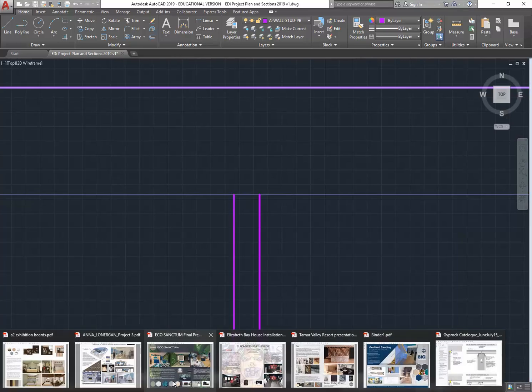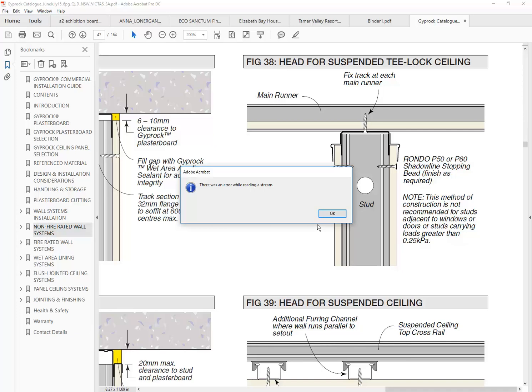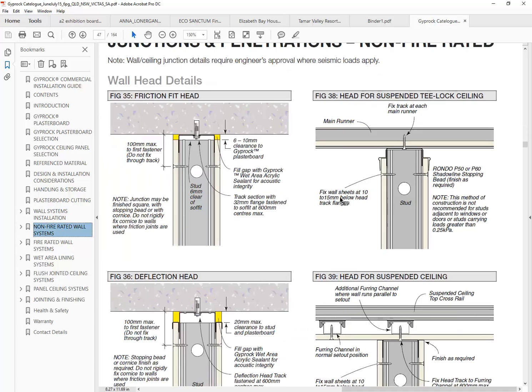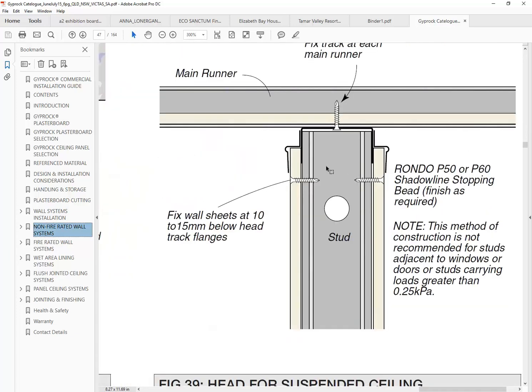And so, again, when you start doing your detailing and thinking about essentially the design features you want, you do need to think about the process a little bit, because if you wanted to have a cornice, it would definitely be worth drawing most of that in your main section and then just copying the section or part of it to get the extra detail. Here, because it's a shadow line, we don't really need much detail for that to be shown in the section. All I want maybe is this rebate, and then the rest of it I'll draw when I copy it over.